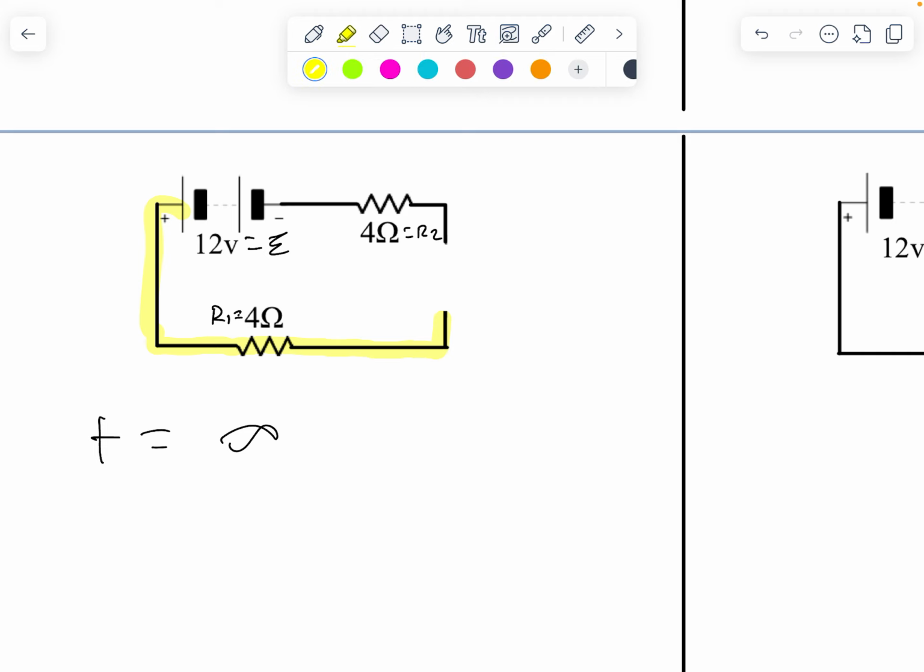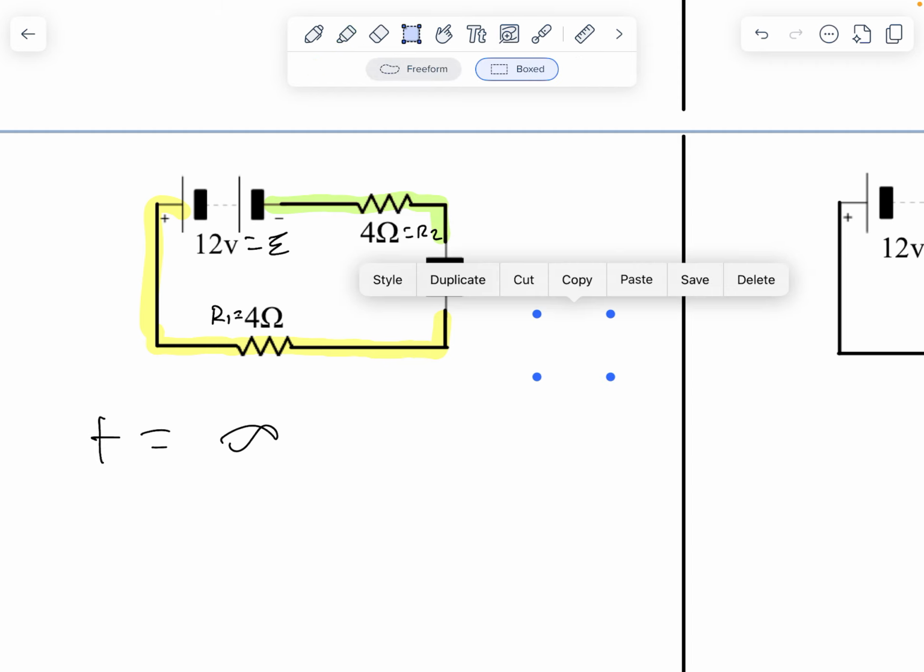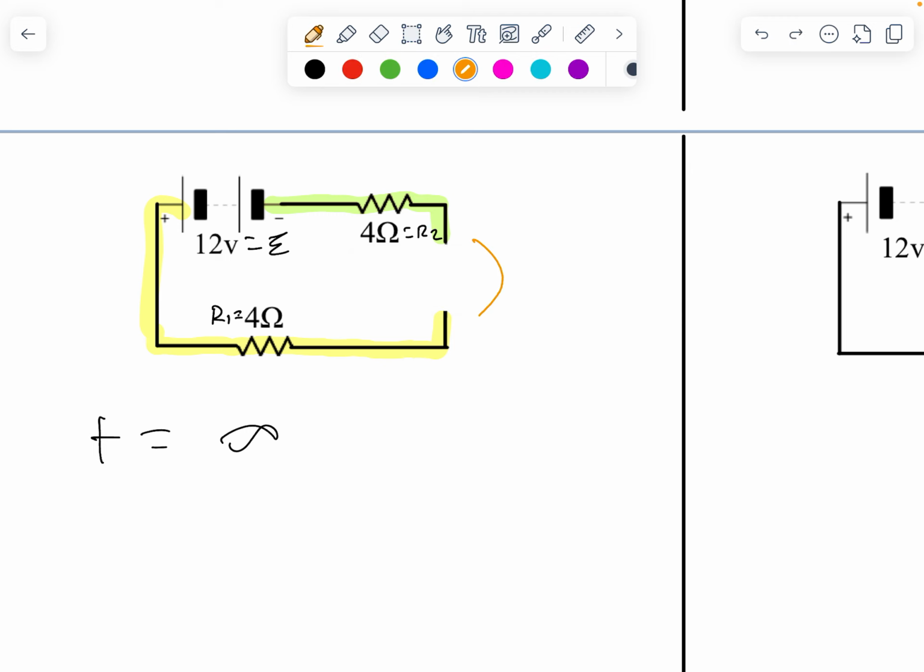So then what we wind up with is the voltage everywhere along here is exactly the same. So what does that mean? It means that there's a potential difference, a voltage difference, across that capacitor. Like I put the little box there just to hide it, but it's not like we took the capacitor out of the circuit. It's just behaving like an open. There's still a voltage across it.